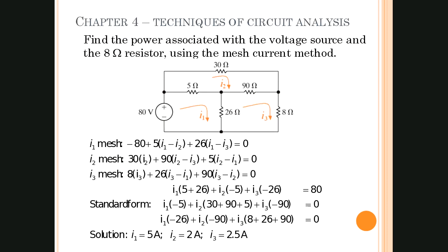And so again, this is the way the author does it. And by convention, and I'm going to let you know to do the same thing, just go clockwise. You can actually get the exact same numbers and the same values if you wrote those currents going in the opposite direction. But you kind of want them all going in one direction, in this case clockwise. If you decided you just like going counterclockwise, it gives you the exact same outcome. Your signs will be different, but everything will balance out.